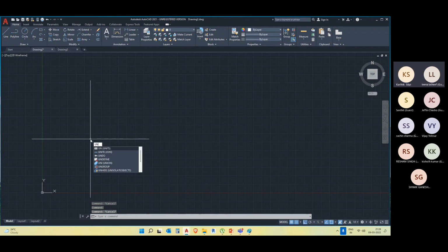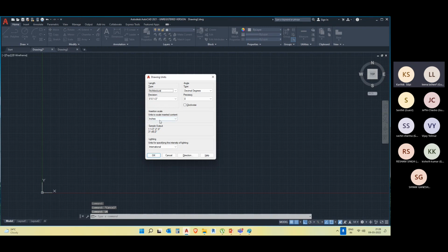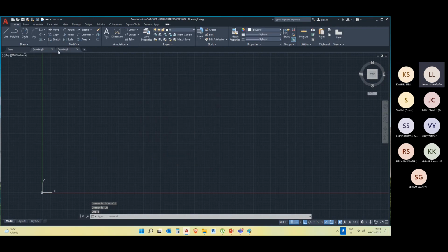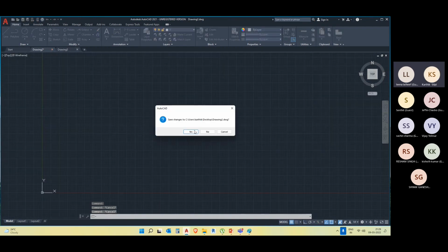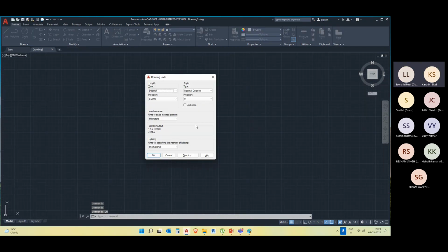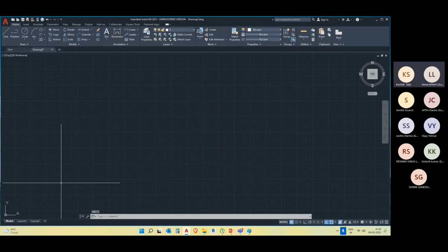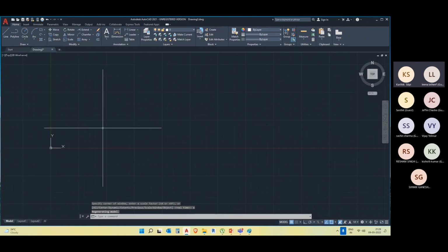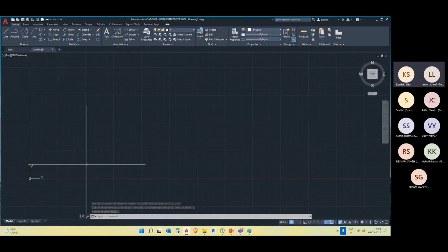So you can say I've set units. It's in architecture. Let me go to one more drawing. Units: decimal, millimeters. Okay, let's set it to meters. Precision is like this. Z enter, A enter. So wherever we are, it will be dragging to our coordinates. This will help guide us to our coordinates so that they will not be missed.